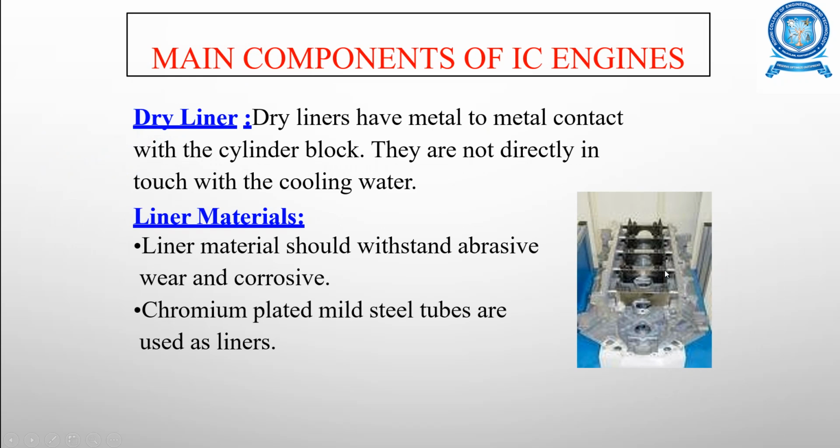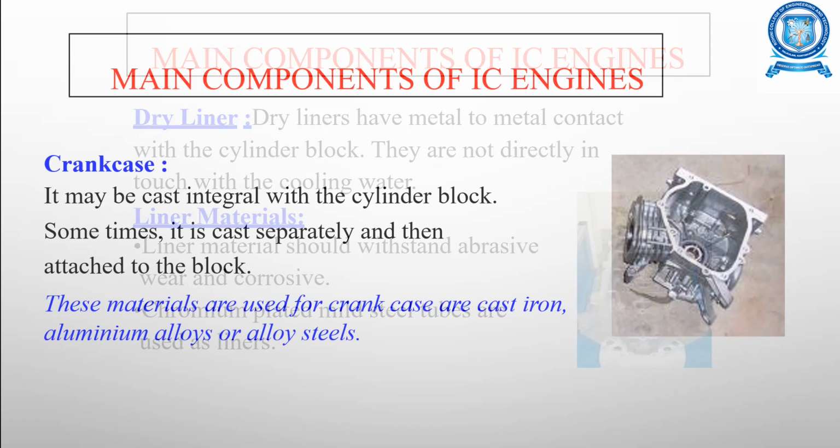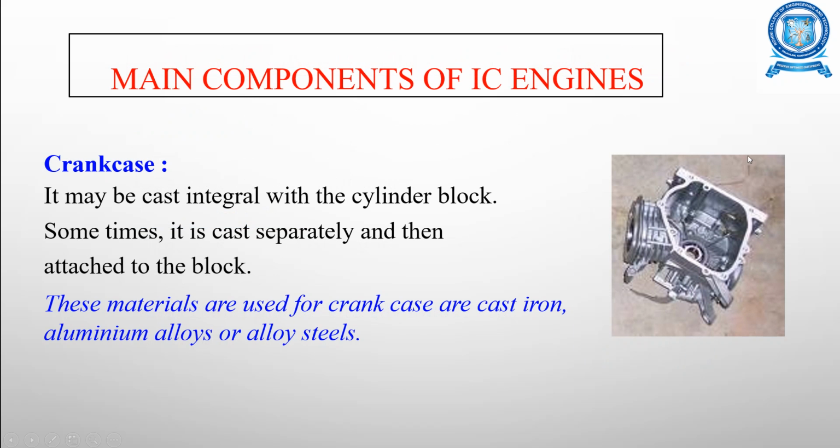So dry liner. Dry liners have metal to metal contact with the cylinder block, and they are not directly in touch with the cooling water. Normally the liner materials withstand abrasive wear and corrosion, and chromium plated mild steel tubes are used as liners.